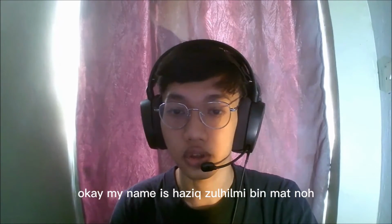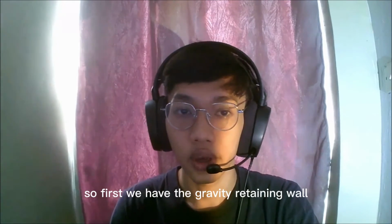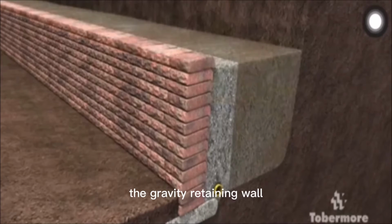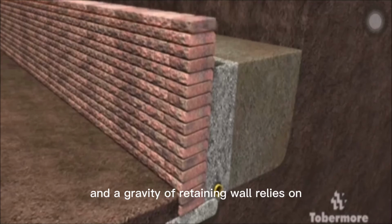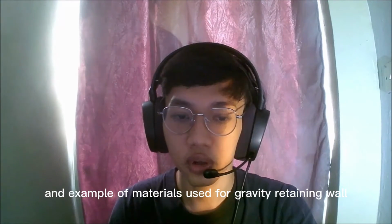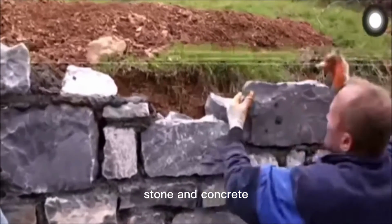Okay, my name is Haziq, and I will continue with the current materials of retaining wall. First, we have the gravity retaining wall. The gravity retaining wall can resist lateral ground pressure, and it relies exclusively on its own weight. Examples of materials for the gravity retaining wall are masonry unit, stone, and concrete.